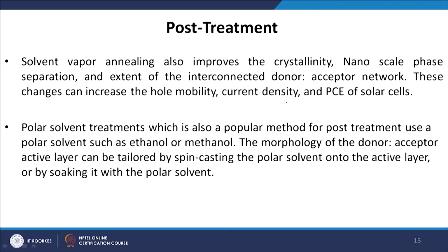Polar solvent treatments, which are also a popular method for post treatment, use a polar solvent such as ethanol or methanol. The morphology of the donor acceptor active layer can be tailored by spin coating the polar solvent onto the active layer or by soaking it in the polar solvent.